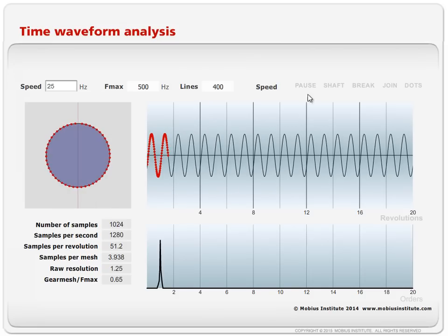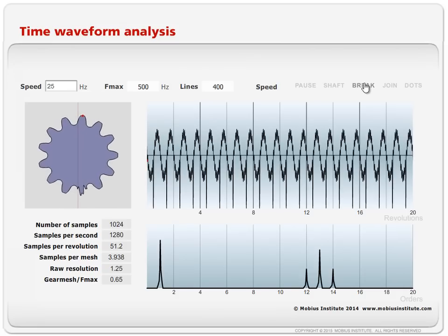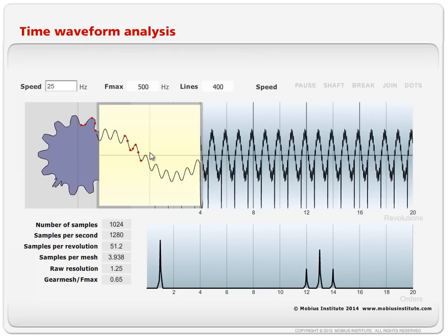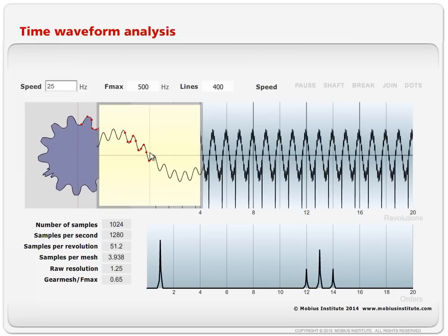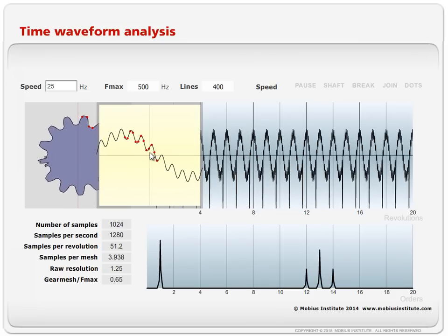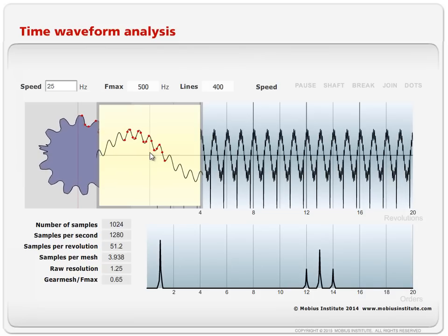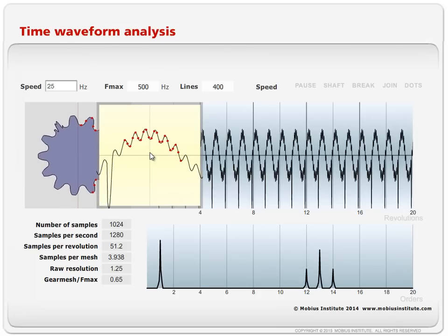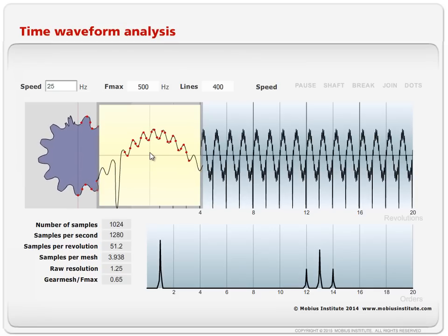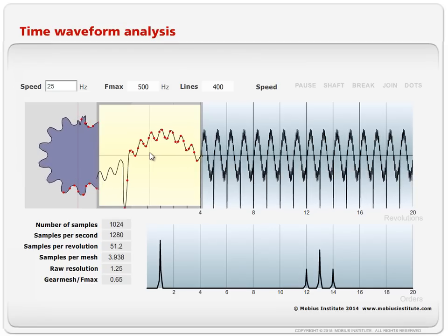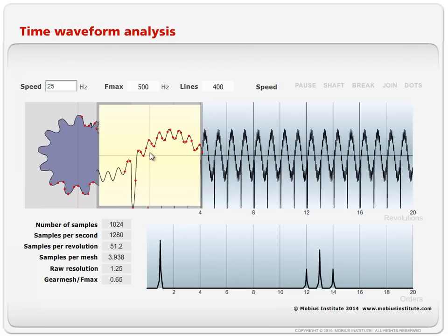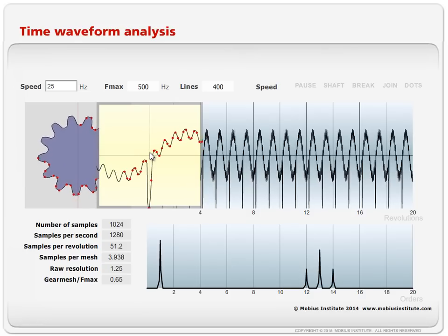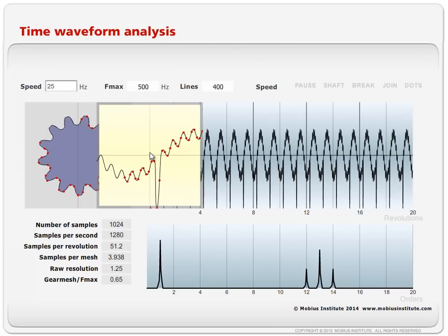So that's all very simple, but what if it was a gearbox, or gear, and there was damage on it? Well, we can translate these little red dots onto the surface of the machine we're testing, because if you can imagine, just as the camera takes a whole bunch of shots, it's also like taking little mini pictures at the gear as it's going past. Now, if you watch on the left, you can see the damaged tooth, and on the yellow graph there you can see that there's only really maybe one or two red dots on that spike of vibration.